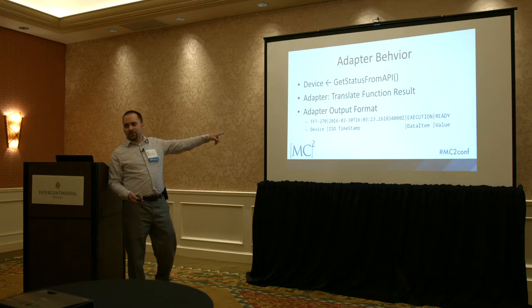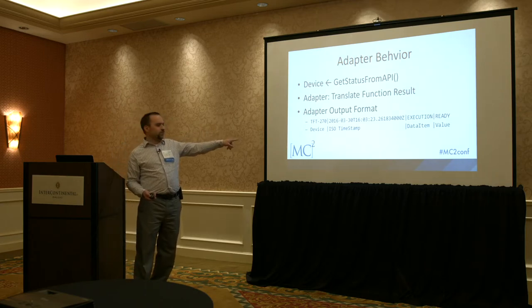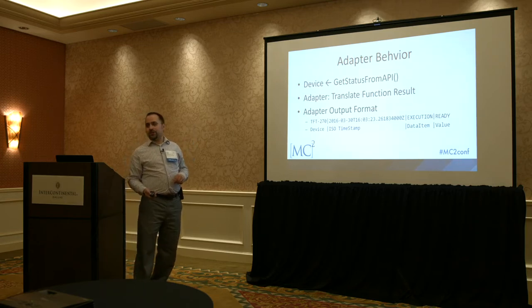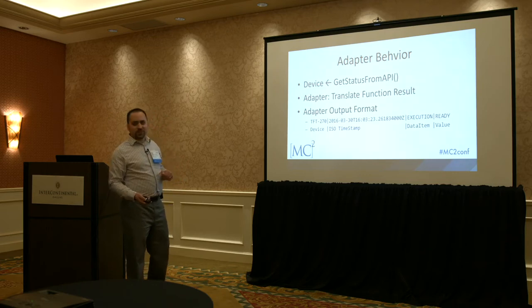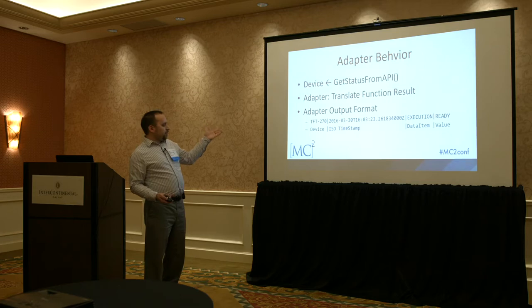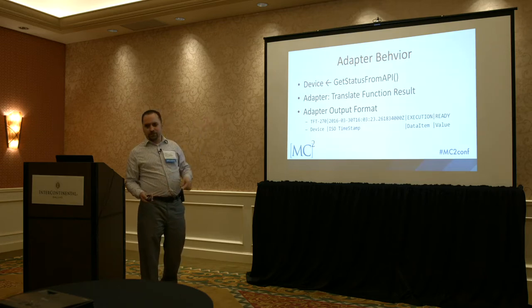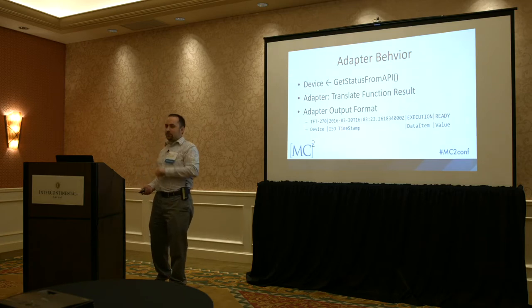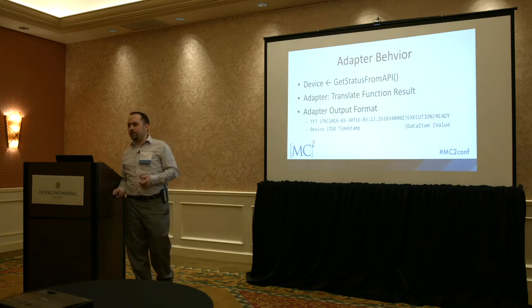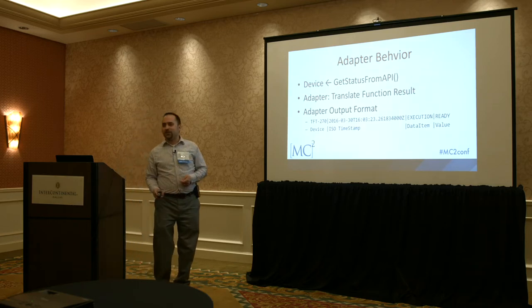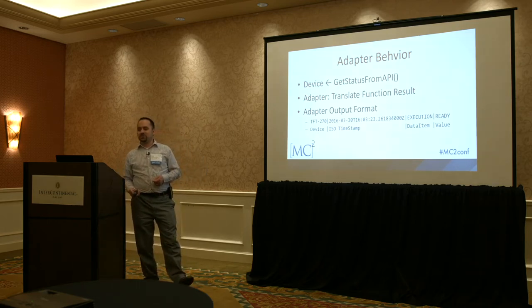Device is optional. In our instance that I pulled this string from, we have a device because we have an adapter that's actually defining data for 26 different machines. So the device is kind of important in that instance. But it's just device, timestamp, data item, value. Nice and simple, lightweight. You can run that thing from a tiny little microcontroller that has barely any RAM and no processing power whatsoever. So it's flexible. We can put adapters on just about anything.